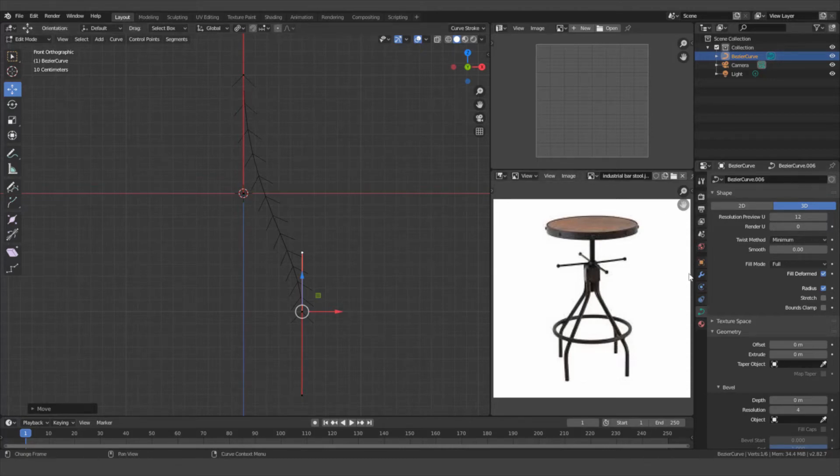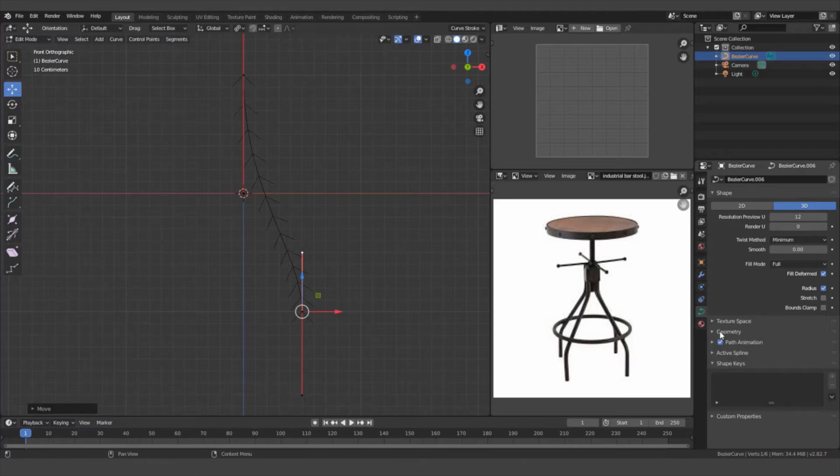Okay, so once we have a curve in our scene, if we come to our control panel over here, we can see that we now have this new control here. If I left click that, I'll get this menu. If I go down to the one that says geometry, it'll probably be closed up when you're looking at it. If I simply click on geometry, come down a little further to the one that says bevel, make sure you open it up. And then we're going to come down to the one that says depth, under bevel, under geometry.